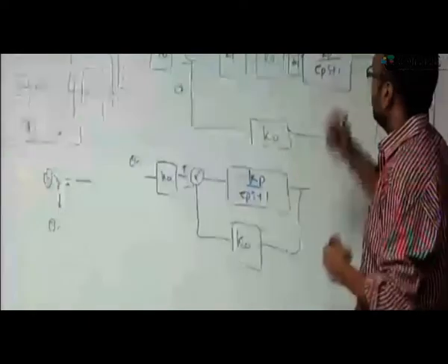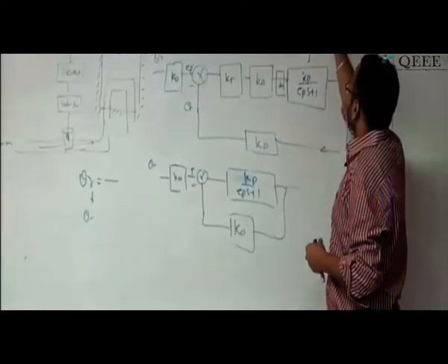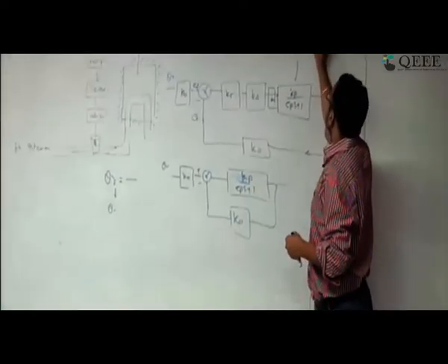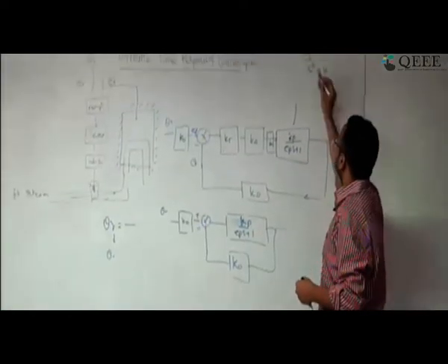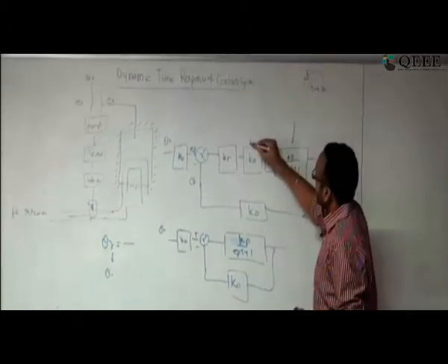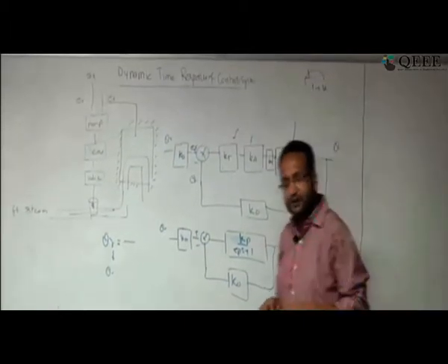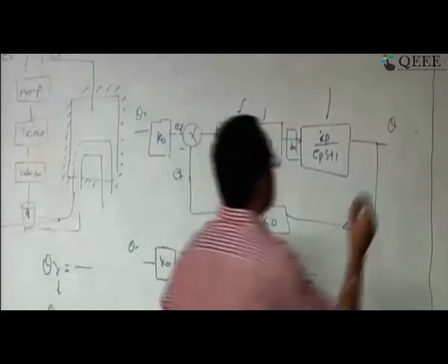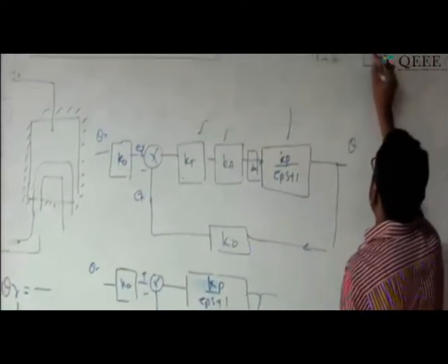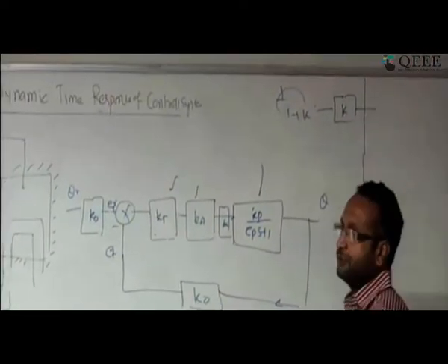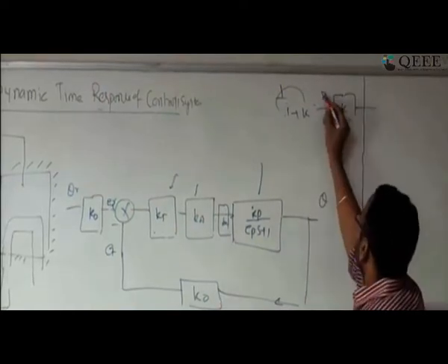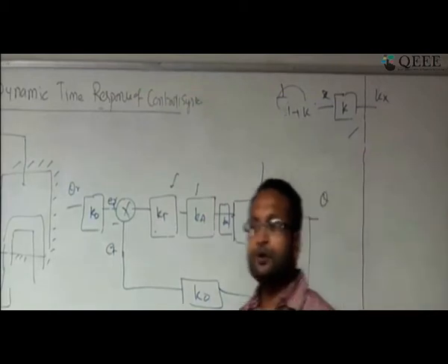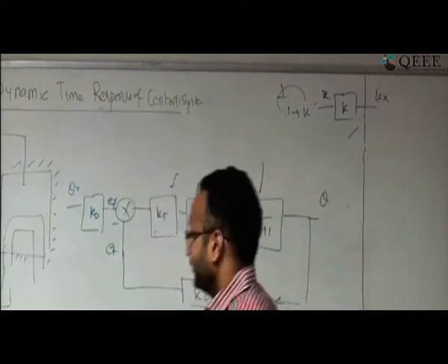This system here is a first order system. So what does it mean? Is there something like a zeroth order system also? Yes, it exists. It means this is s to the power of 0, some constant, and this term is going to be 1. So this is a zeroth order system. What does a zeroth order system mean? It means the system will respond quickly, as the system gain is just some constant. So if you give the input, the response will immediately be k times the input. Suppose I give the input x, the response is going to be kx. So the zeroth order system is going to be very fast. Correct?